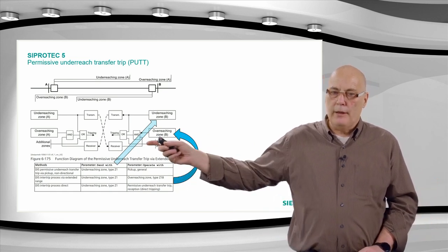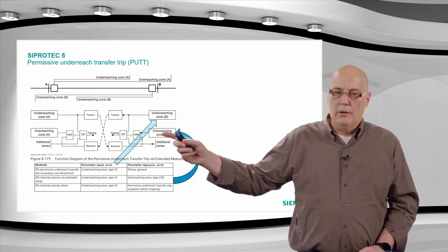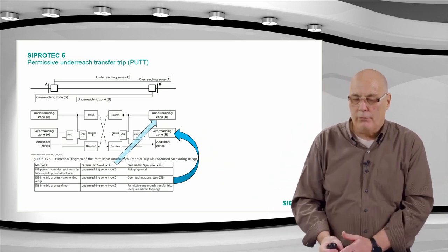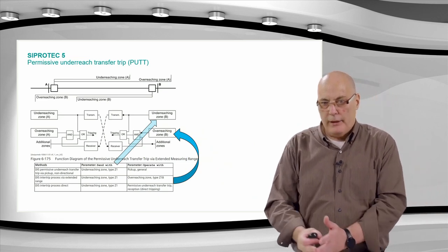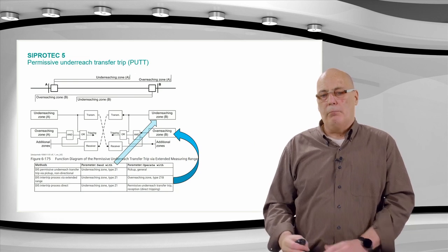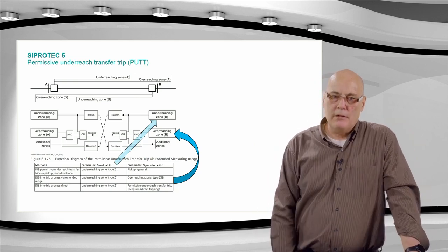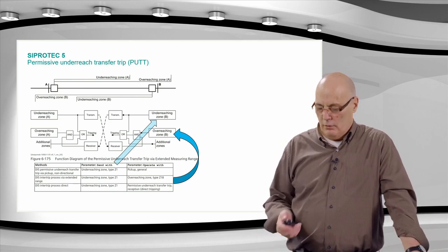So you put that received signal into a zone 1 overreaching zone release, and that means that the chances of that unwanted command coming from one of your 10,000 relays once per year and an overreaching zone pickup at the same time, that is not likely. That's like winning the lottery 3 weeks in a row, effectively.